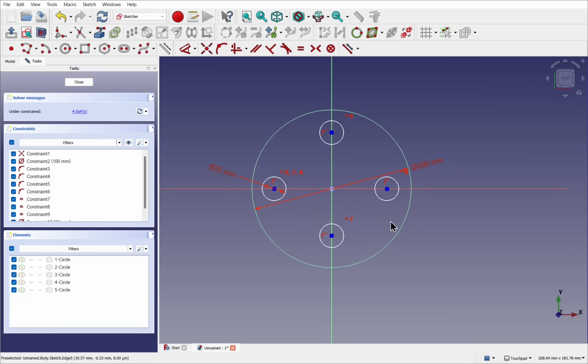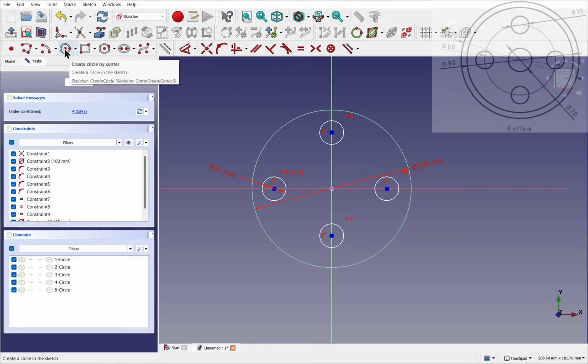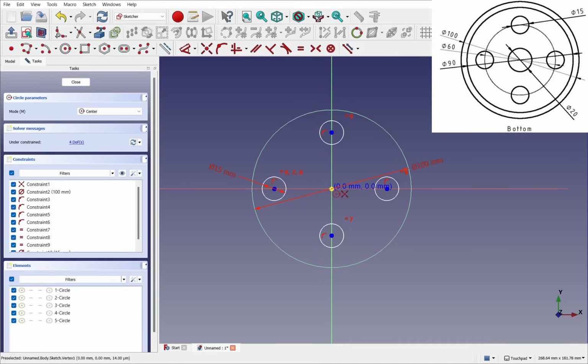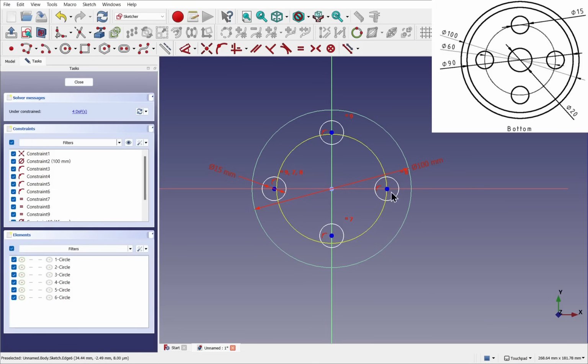We're going to use something called construction geometry. Now, construction geometry is just for that, construction. So we'll select the circle, hover over the center point, make this coincident, and drag the circle out. So before I drop this, I'm going to come up and connect to this point here, this circle. That will make this circle have a point on object constraint to this geometry, which will make construction. Right click to cancel the tool, and we can see how that moves with that circle.